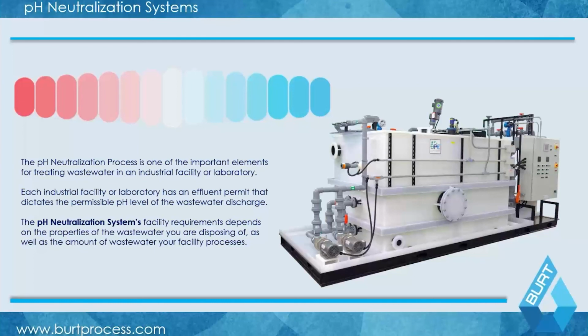And your pH neutralization is really what accomplishes this. It's in line, in your actual drainage system. It allows you to treat any kind of waste streams coming into it from a pH perspective, as well as a few other aspects such as temperature. But it is an integral part of meeting compliance for any of a number of different types of facilities.